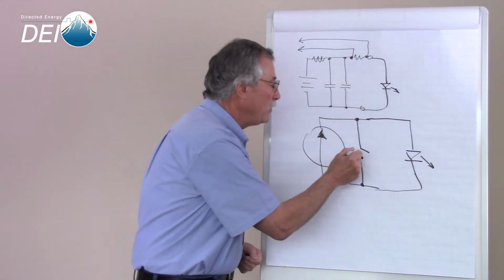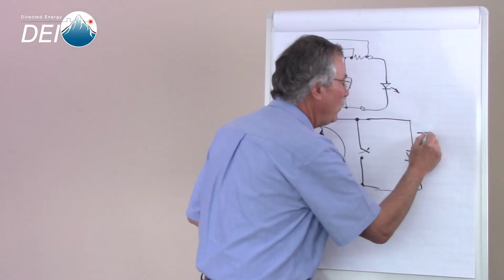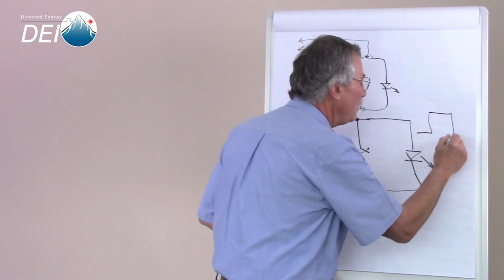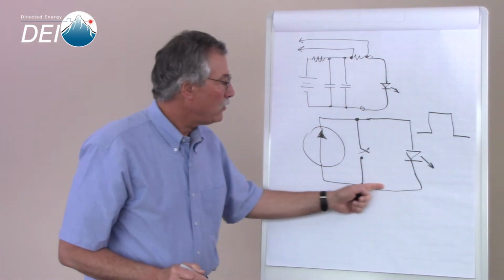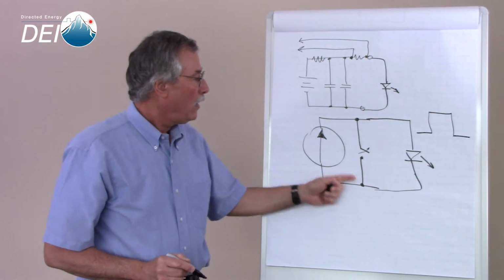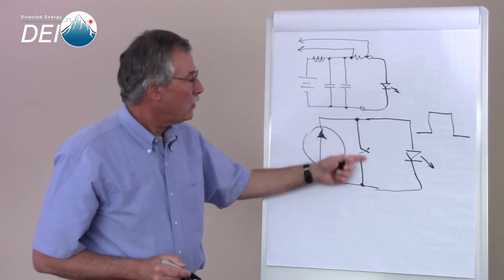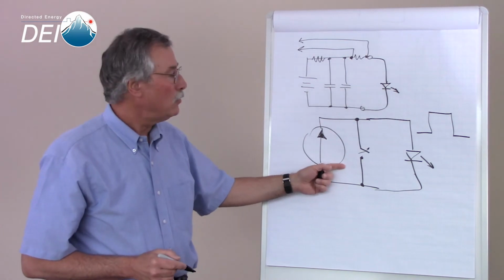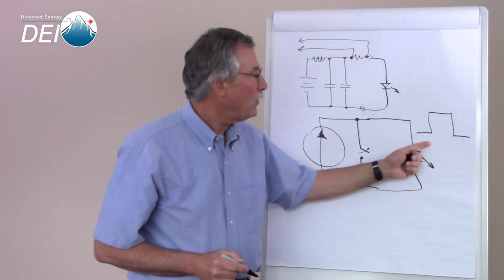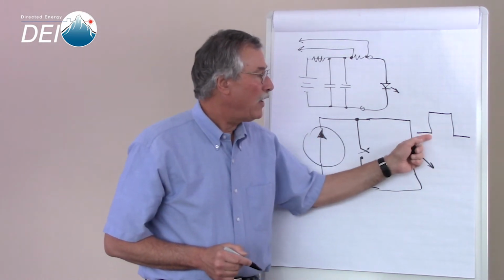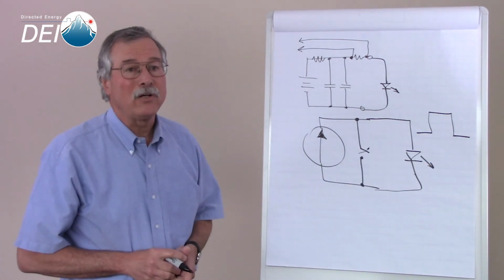What we do is open this switch briefly. We go from zero current to full current, running it through the laser diode through this larger loop. And when we're done and we wish to end the pulse, we close the switch, the current goes back to flowing in the small loop, laser diode goes to being off again, and we end up with rather fast rise and fall periods.